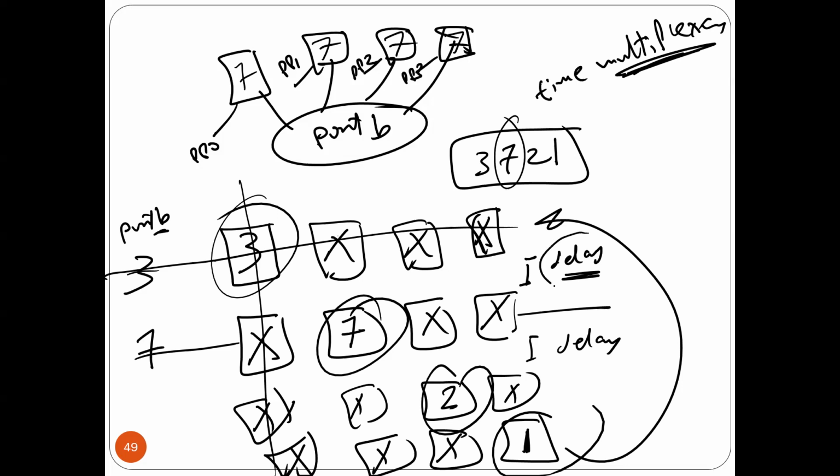Okay. But the point is that, why do you need a delay here? That's a question. Why do you need a delay? Okay. We need a delay because the microprocessor is very fast. If you just put a value and remove it quickly, if you put 5 volt, remove it quickly, what's going to happen is the 7 segments are going to become dim. Why? You have to keep the voltage, the 5 volt, for some time so that the LEDs can get the brightness. Okay, I told you before.